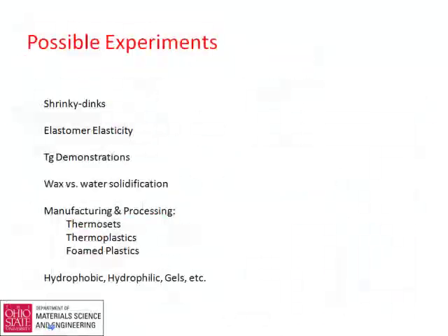So here are possible experiments you can do in your classroom. I mentioned shrinky-dinks. Another one you could do, I don't think this one was written up in the ASM handbook so much, is elastomer elasticity. You actually find out that if you heat elastomers up, they become stiffer, and that's because entropy basically is a more important driving force as temperature goes up.